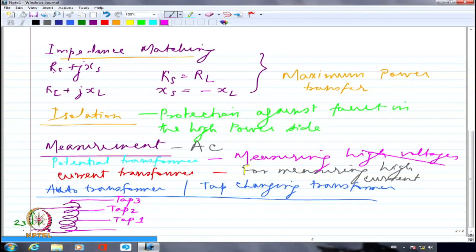When I am having 400 kilovolts at the output on a nominal load, say 100% load, obviously there will be some internal drop within the transformer, within the generator, because all of them are having some R and some jX. So depending upon the current that these equipment are carrying, I am going to have some drop.